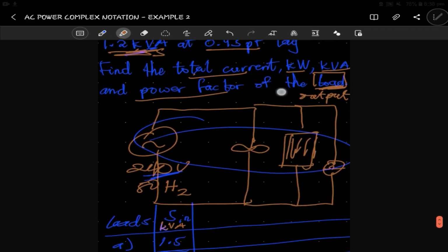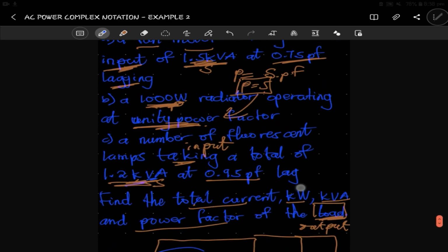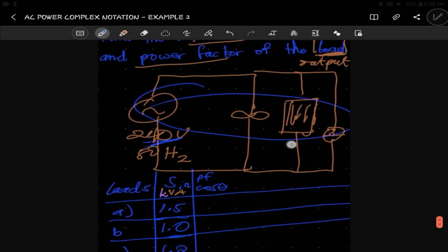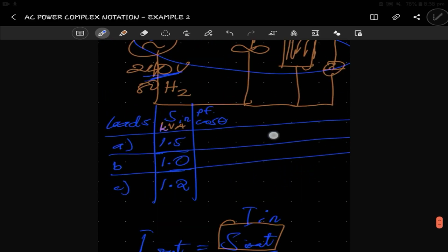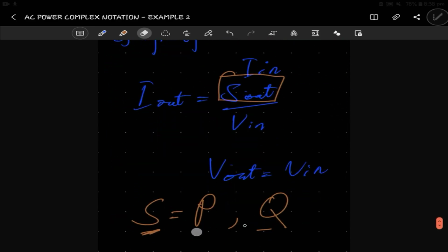Now for us to do that, we have the S, so we need the power factors. We have the power factors already, which you know to be cos of the phase angle. For A, we have that to be 0.75. In fact, we have those values already, we don't even have to point them out again. So, straightforward, to find our S, we need P and Q.